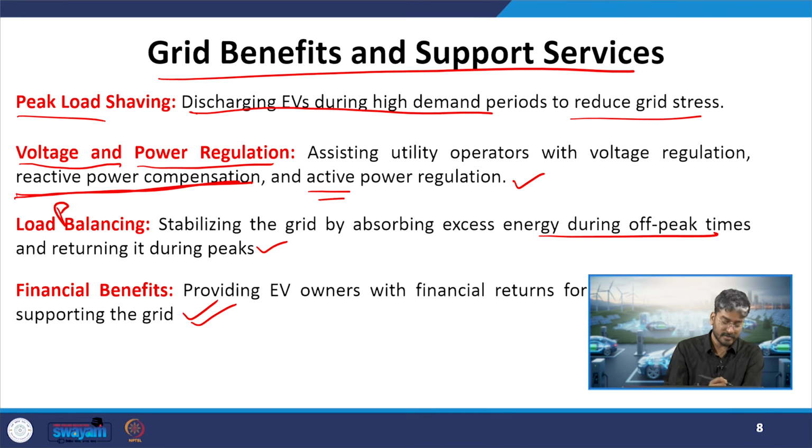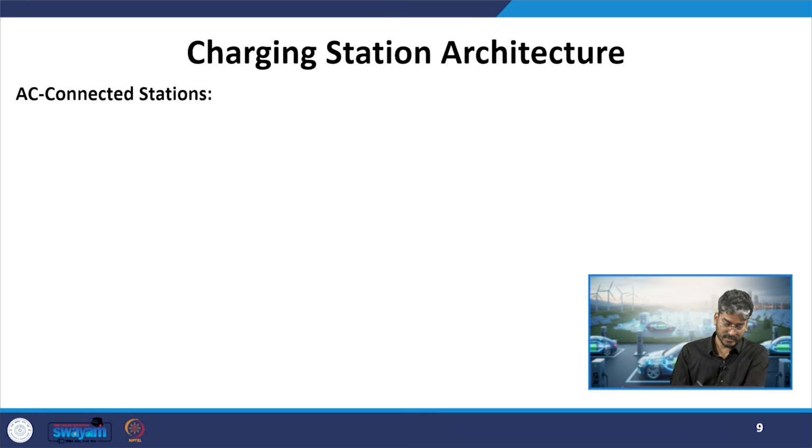So, during the mismatch, there is a high possibility of power mismatch, or whenever we are having peak loading, that is when the generation is not sufficient to meet the load demand. During those cases, these EVs are more necessary to improve the stability of our grid. So, that is why this concept of the vehicle behaving as a source has come into the picture.